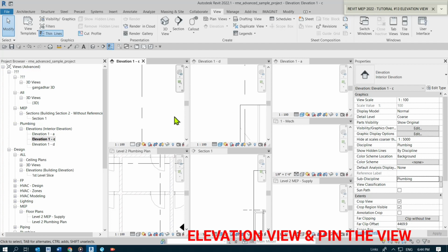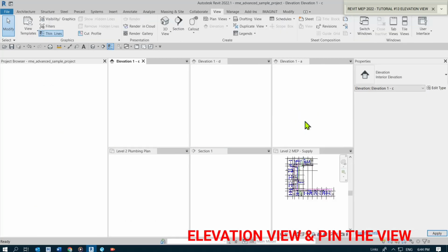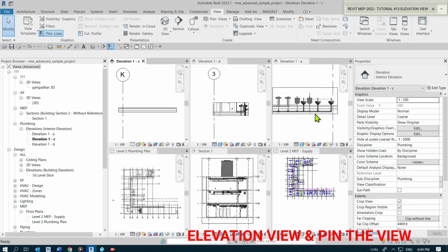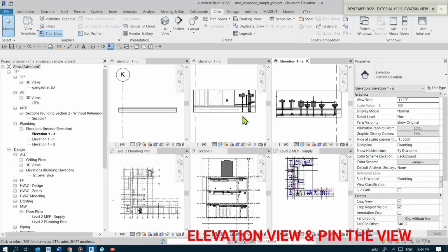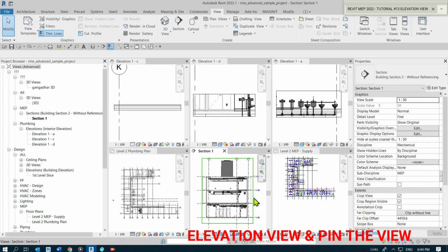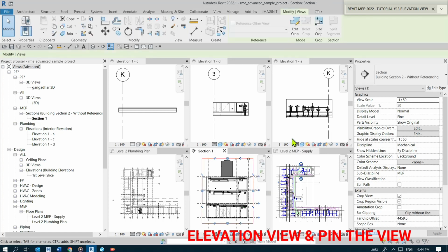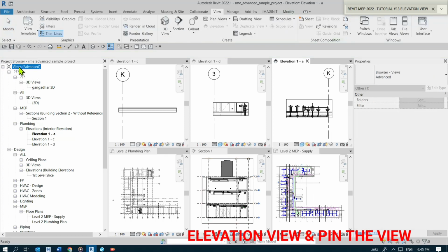I can type WT to tile the view. So you now have here your section and then you have your elevation. Just for best practice, when you are creating your section and elevation, create them to check specific design areas during the design development. You can create a temporary section and elevation view types in the project browser to segregate the temporary views.